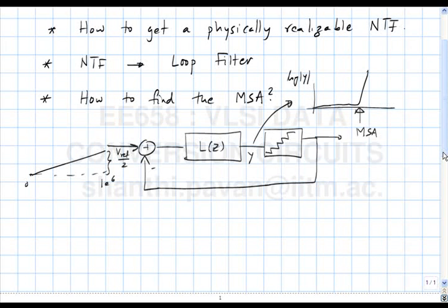Okay. So traditionally the 1-bit quantizers were the first to come, simply because of the ease of implementation of a single bit quantizer. It's just one comparator and you're done with it, right? So a lot of early work in delta sigma modulation is all based on single bit quantizers. Multi-bit quantizers were thought to be difficult to do and difficult to implement, and were also associated with a few other problems. I will come to that when I get there. But over the last few years, people have realized that multi-bit operation offers a lot of advantages over single bit modulation.